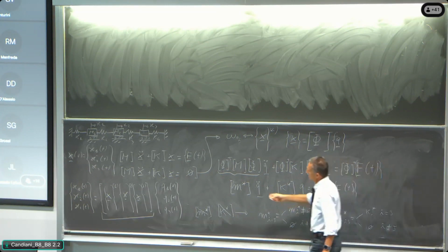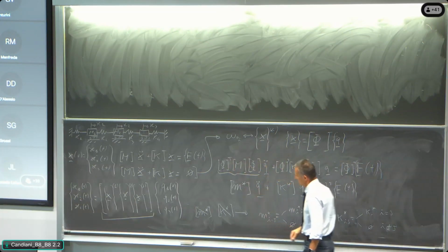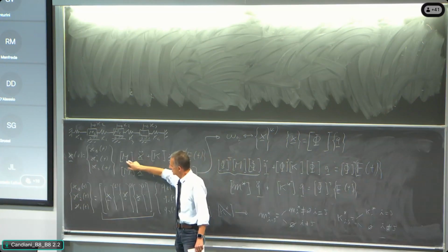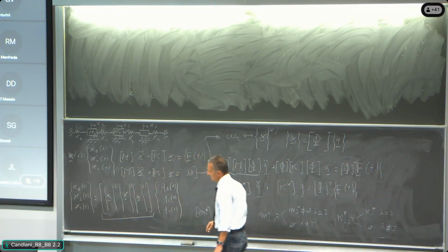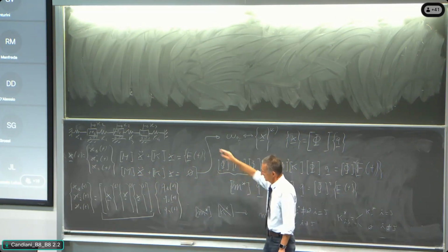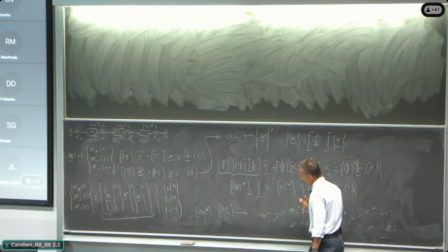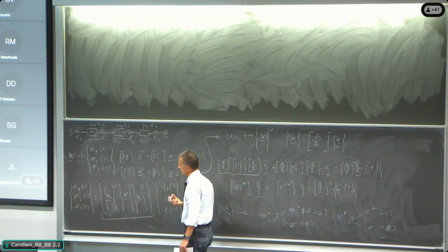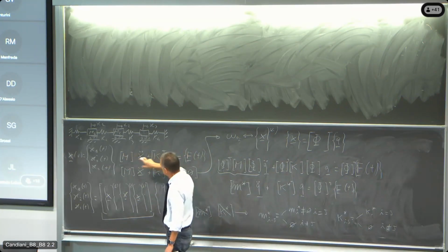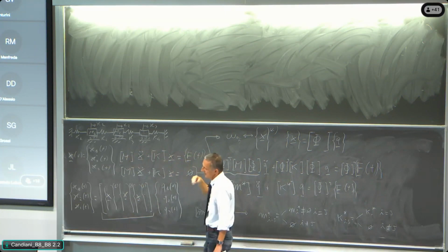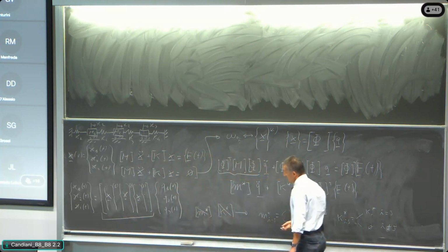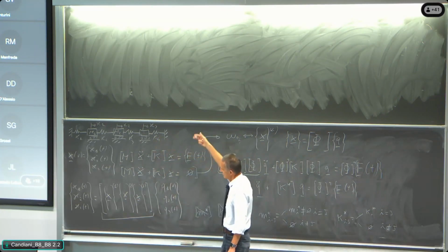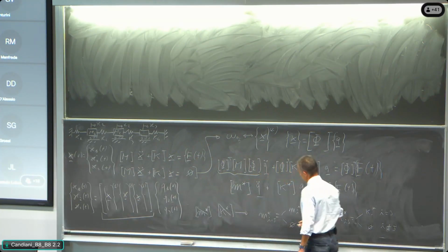So making this product of phi transposed times the mass matrix times phi, given that this matrix was derived and is symmetrical, as it was derived by the Lagrangian operator applied to the dynamics of the system, there are some constraints that we have to give. The fundamental constraint is that M and K must be symmetrical, and they must be derived using the energetic Lagrangian approach over the system.